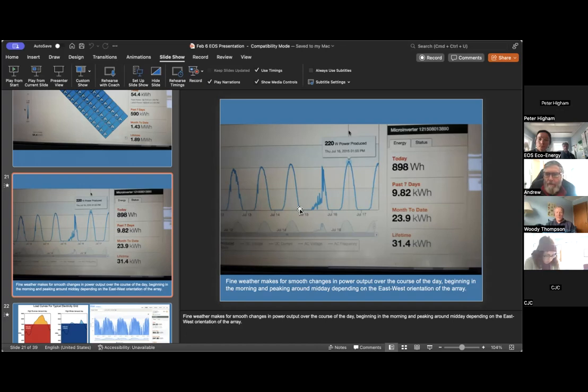Metal roofs are easy to work on. They're more challenging than asphalt in that if there's a bit of precipitation, you can't walk on the typical metal roof. But if you have a dry metal roof or a nice day to install, and it's facing in a good orientation to the south, that's ideal. For a couple reasons, one of which is that asphalt roofs, despite the manufacturer's claims, do not last very long, and by very long, I mean 30 years or 40 years. Typical asphalt roofs last about 20 years, and you will have to get it replaced, and then when that happens, you'll have to have the solar array removed. So metal is better, in my opinion.